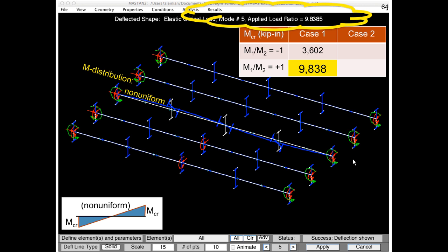If we go to the other end, we've got load on here, and now the top of the beam is in compression, so the top flange is buckling, and the bottom flange is in tension, and we're getting that twisting to occur. So that's about as much detail as I can give you at this point of what we're seeing there. It would be a little more fun if we had more elements and could see more of the actual twist profile along the length.